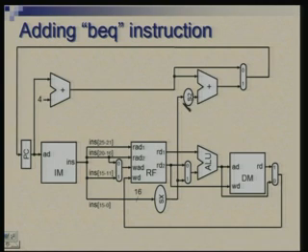So this, as I had discussed earlier, is a matter of simply wiring things correctly. So we have the correct offset coming here, which gets added to PC plus 4 and is available to this multiplexer. Now this multiplexer has to look at which instruction it is. If it is not a branch instruction, it will simply allow this to go through. If it is a branch instruction, then it looks at the result of comparison in the ALU, and accordingly a 0 or 1 will be chosen here.